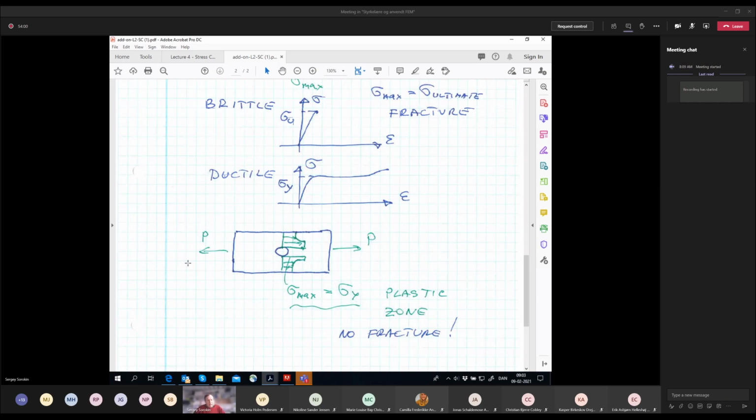And the simple cases are the change in the temperature. If you take steel and make it quite cold, much sub-zero, then it turns brittle. It loses its ability to perform plastic deformation. And if you apply dynamic loads, if you apply loads very, very fast, then it also loses the possibility of this plastic deformation.